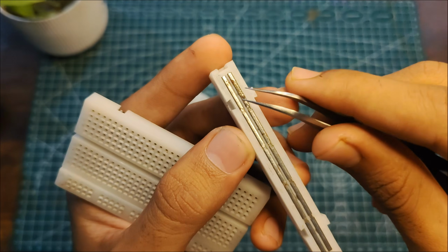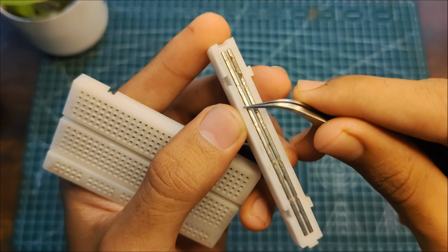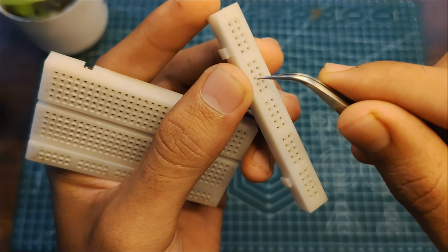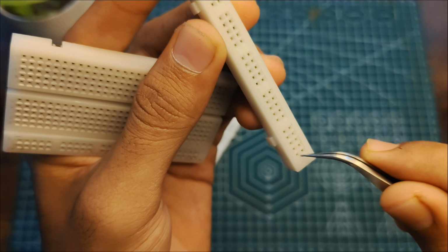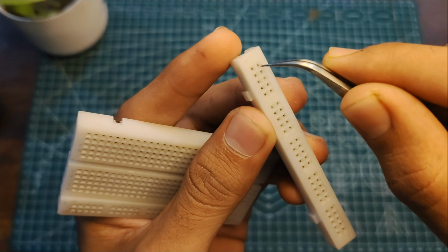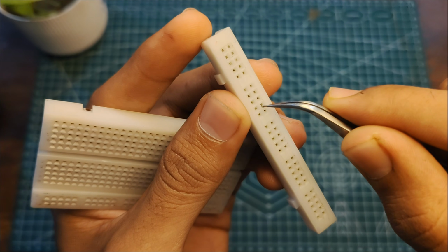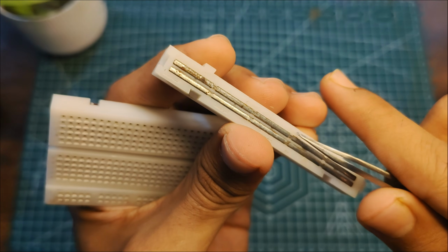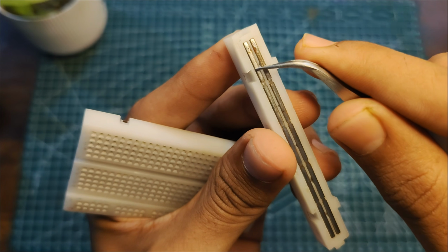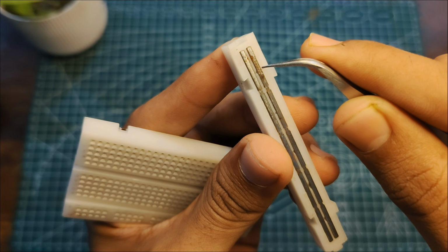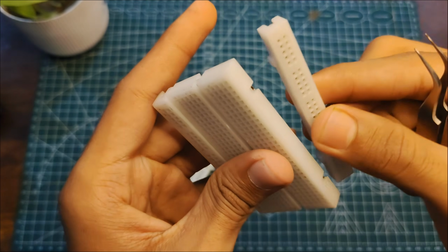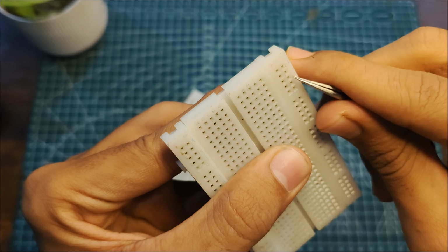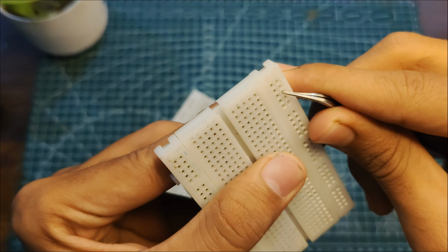So here you can see when I flip the power rail, there are two different connections which are continuously going on. So it means all of these vertical holes are connected with each other, and all of these next consecutive holes are connected with each other. So there is a gap between both of these connectivities. So we can use one of them as a 5-volt power supply and another one as a ground. So we just need to attach it back, and we can give it a 5-volt, and the next one could have a connection with a ground.